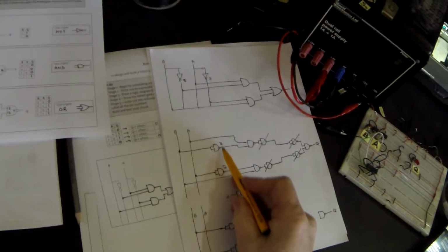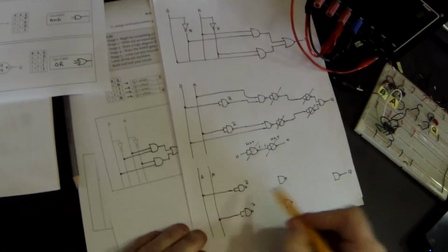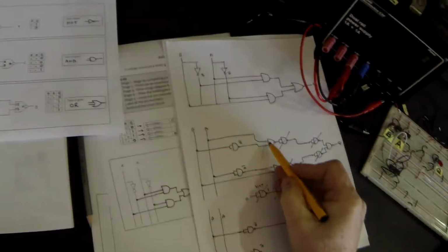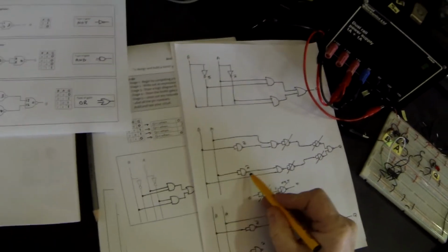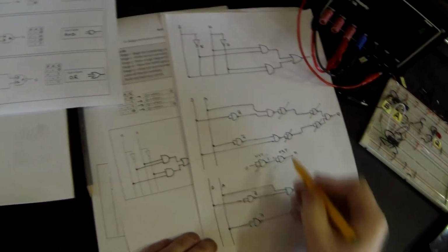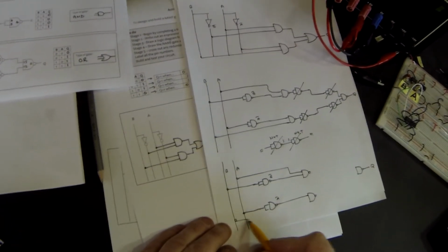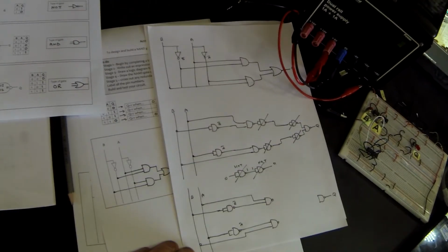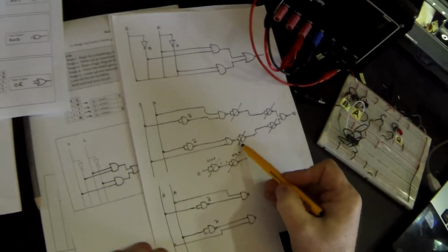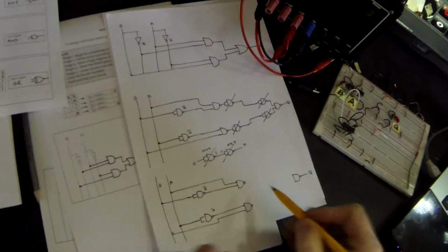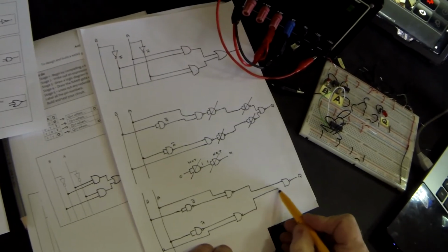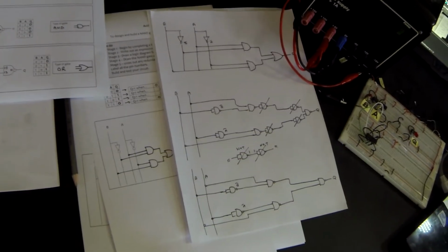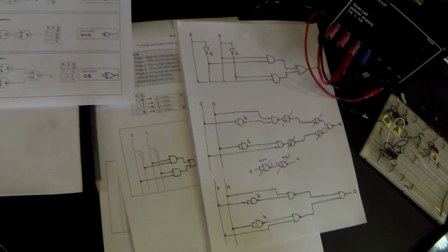I'm trying to draw them in position so that you can see where they all are. So this NOT B here is going to feed directly into this input here, and then the other input came from A. This NOT A fed into this input here, and then this other input came from B. We had our two NOT gates on each of these lines, but they are now all gone. So all I need to do is connect where they were from and to, and it looks like that. And immediately you can see we have simplified this circuit no end.